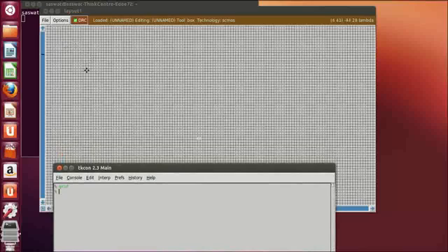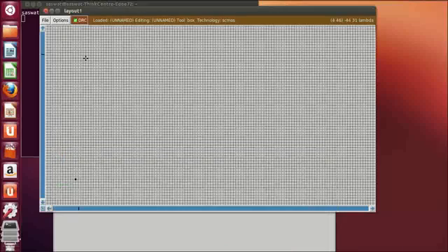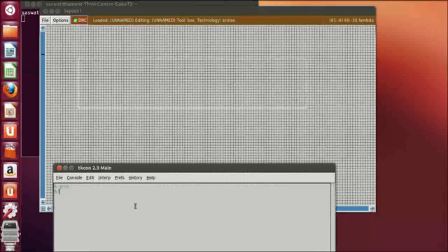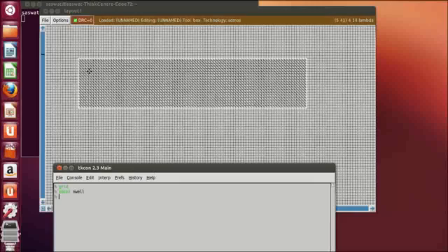Now, at first we have to create the n-well region, so we have to select the area. Since this is a 3-input NOR gate, we should keep the n-well in a larger area, and next also the P diffusion layer. So left click and then right click. There will be 3 poly layers, so 1, 2 and 3, so we need a bit bigger one. Now we have to type paint nwell. So the n-well layer is drawn.